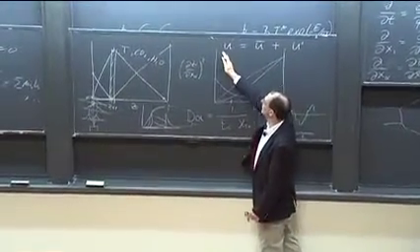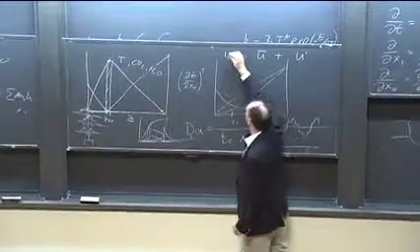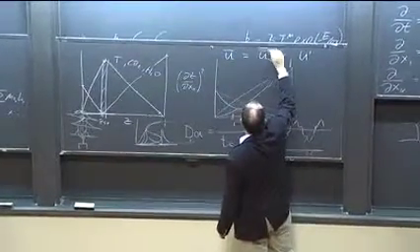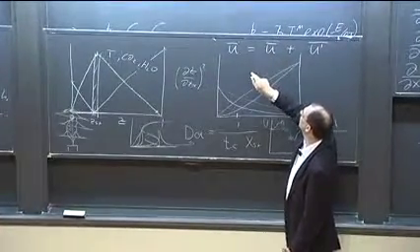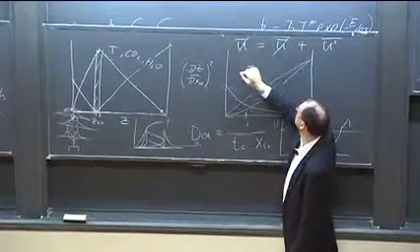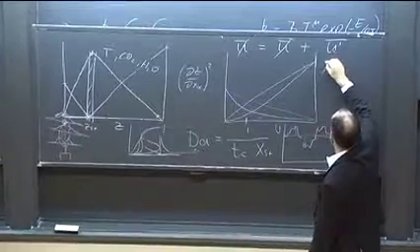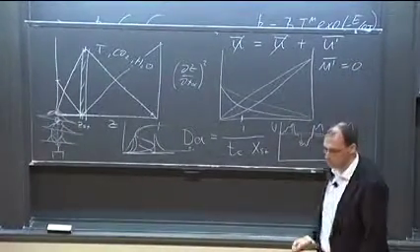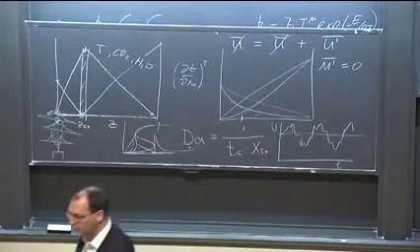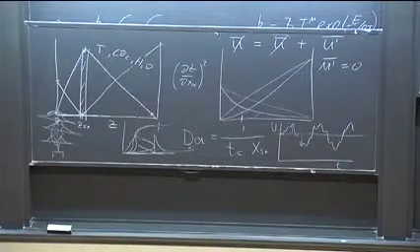So if I take the mean on the left and on the right side, this here is again the mean. These two cancel out, and the result is that u prime mean is equal to 0. So that's the assumption in the Reynolds decomposition, that the mean of the fluctuation is 0.